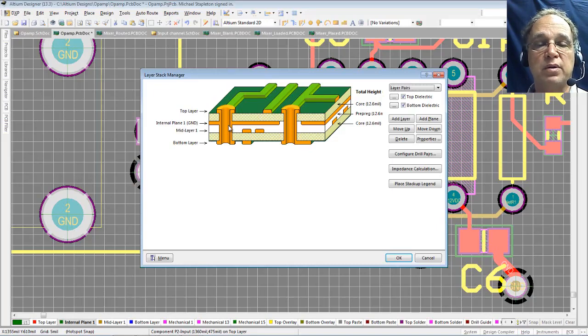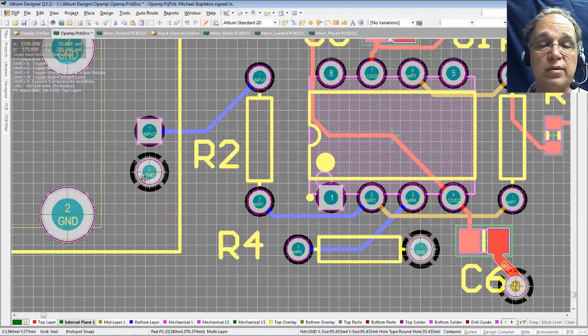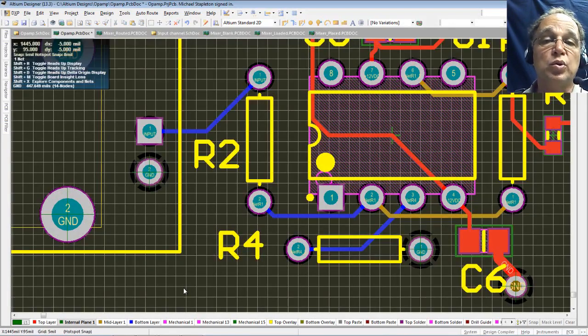And that takes a while on a big iron, and it may get hot enough long enough to start delaminating the copper off the top of my board. So the way around that is to put these little spokes. Now I have a nice electrical connection, but I don't suck all the heat out. I can solder my parts. So that's my internal layer.